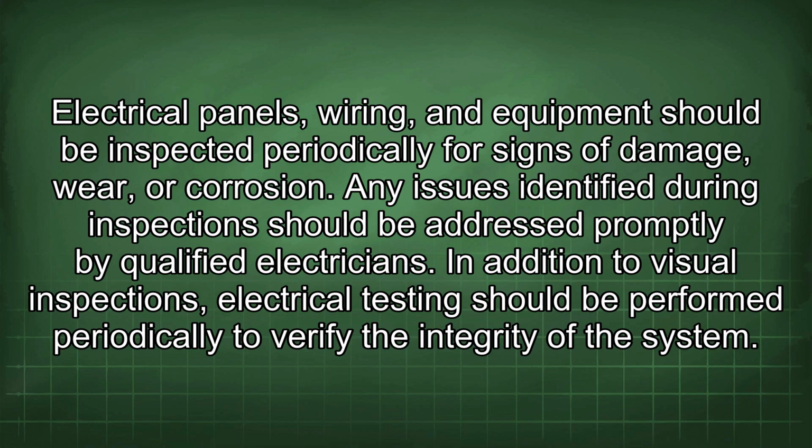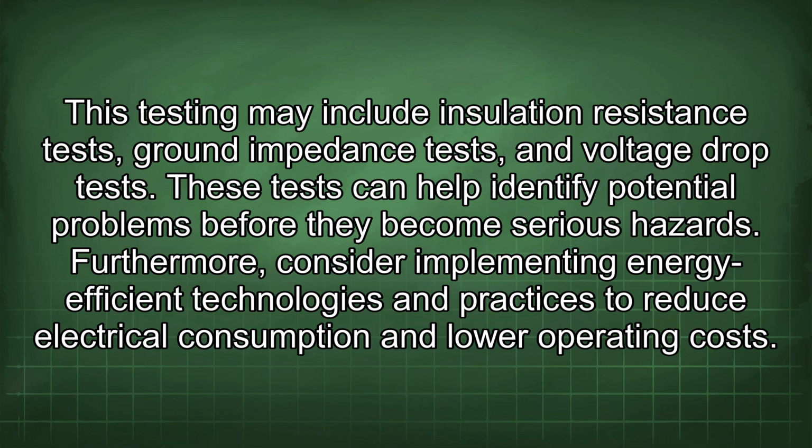In addition to visual inspections, electrical testing should be performed periodically to verify the integrity of the system. This testing may include insulation resistance tests, ground impedance tests, and voltage drop tests. These tests can help identify potential problems before they become serious hazards.